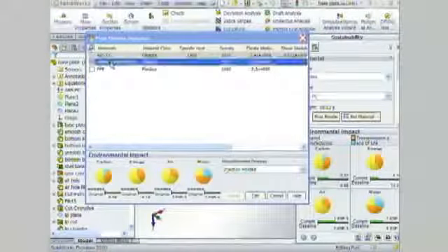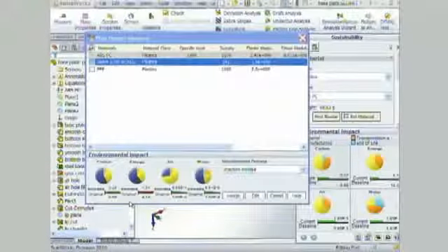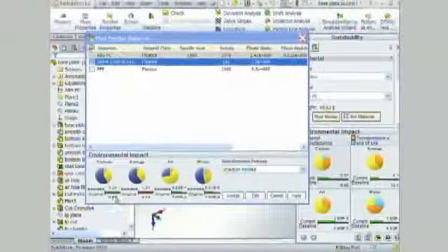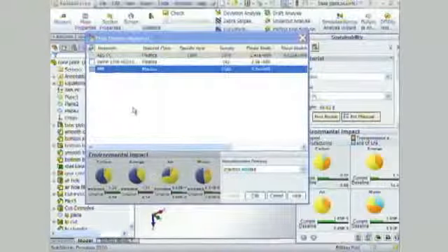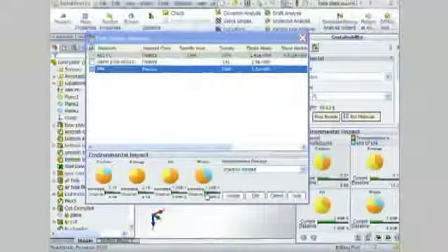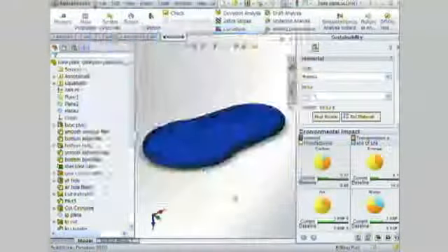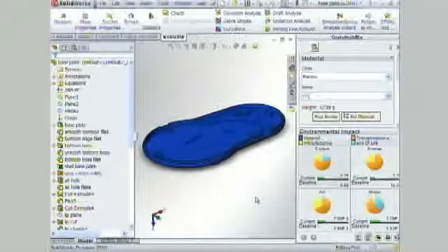Cool thing is, when I select on a material, you can see the dashboard update to reflect how this new material compares to the old one. So I can look at the green bars and I can see, okay, this material is marginally better and actually worse in terms of energy to the original ABS polycarbonate blend. How about the PPE plastic? When I select on that, I can actually see it's notably better on all environmental impacts. So that's the material I want to go with. So we'll accept it. We can see the dashboard down here update to reflect that change, and on we go.